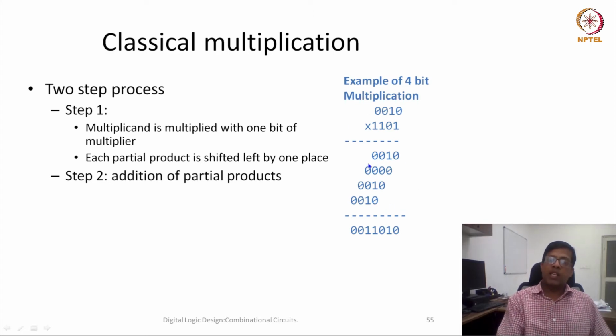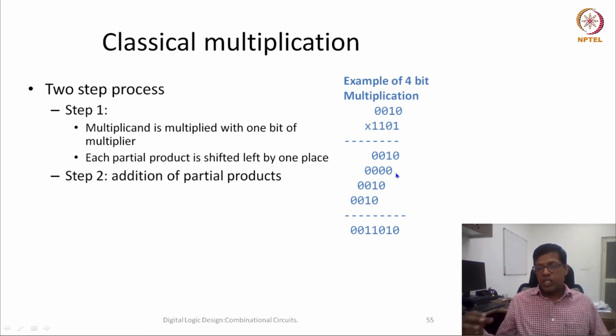In other words, every time this is supposed to be an 8-bit addition, and after adding one partial product, another partial product is added. If we consider our partial result as an 8-bit result, then every time we are adding the shifted multiplicand.